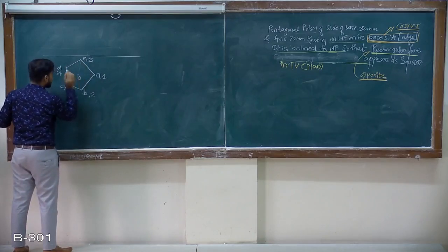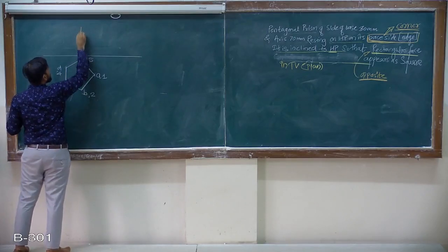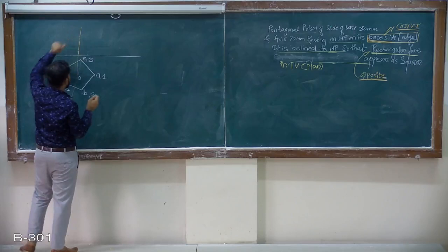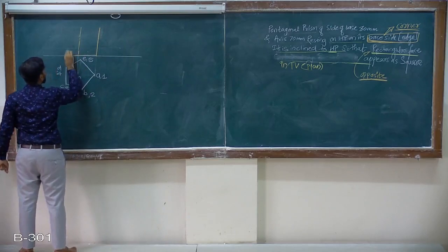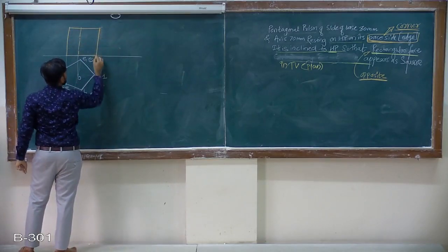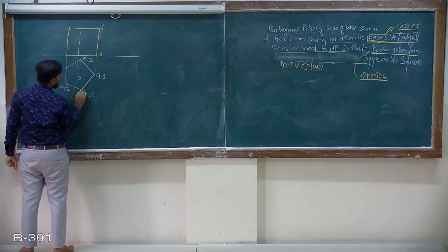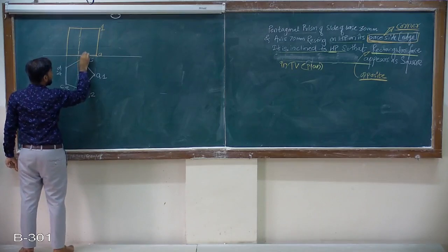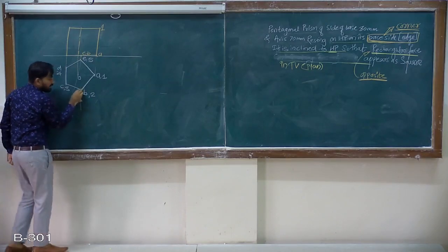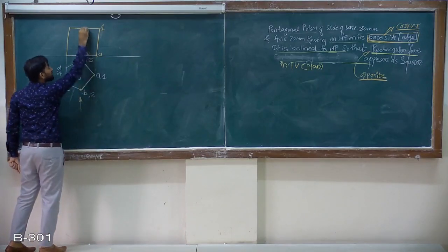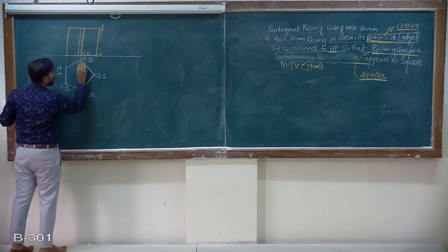corresponding face edges, find out the axis point. Just let's say O. Project the axis. So on this axis, I will mark the axis height as 70. So this point will be corner A. This will be the opposite corner 1. This will be E comma B. As the observer is here, this is the nearest point. So I can see this edge as a continuous line.